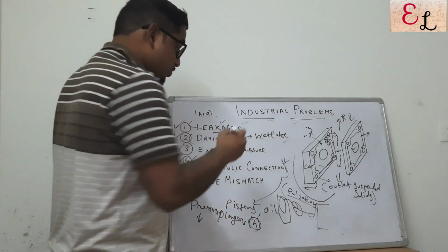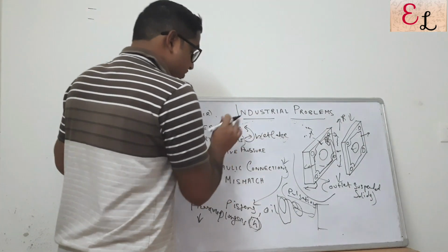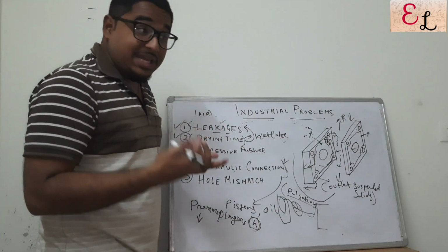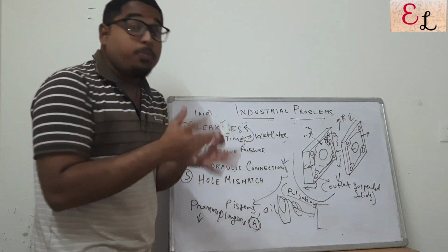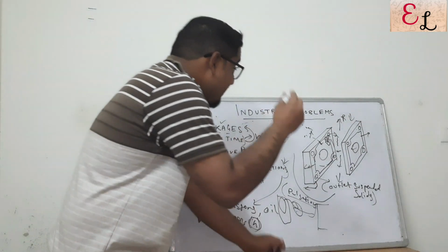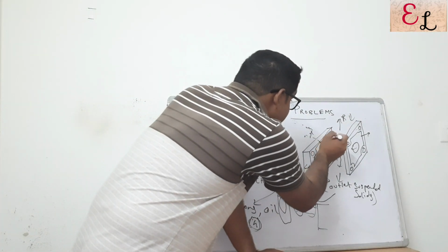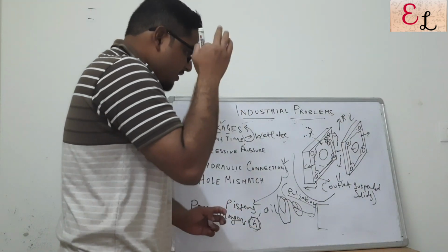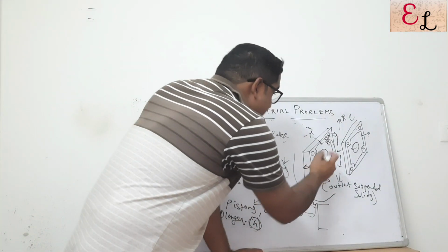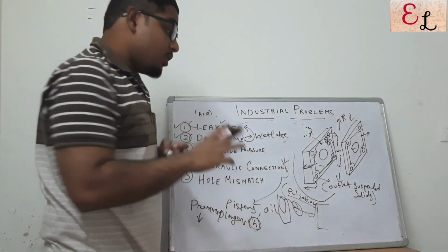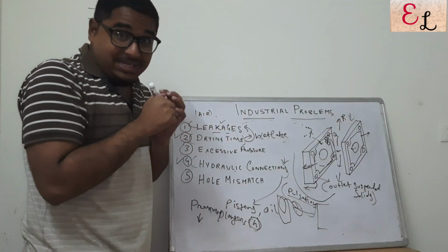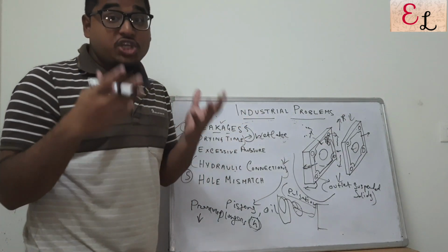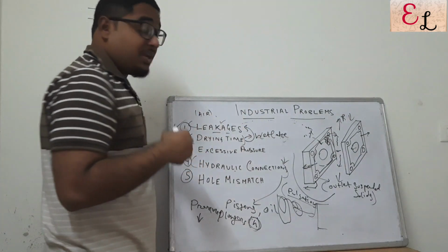Now, why has this problem occurred? Again, interlinked, primarily due to leakages. And why these leakages? Because the air has not passed through the cake, but might have escaped out through this porous gap into the drain point and drained out of the system, firstly. Secondly, it might have escaped from the side or the top of the plates and might not even have passed through the cake, and hence didn't carry out the moisture with itself, and the cake takes a sufficiently higher amount of time to dry itself off.